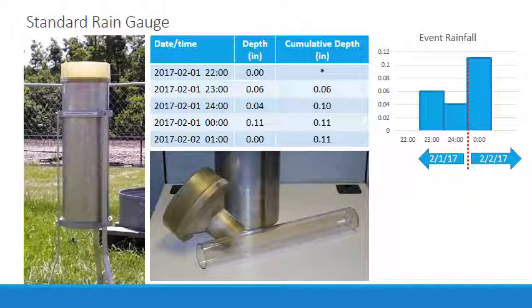Consequently, rainfall depth is magnified 10 times, which helps you read the measurements more accurately, to the nearest 2.5 hundredths of a centimeter, about 1/100th of an inch. When the amount of rain is less than that, it's generally reported just as a trace of precipitation. So in the database, you'll see a TR instead of a number.